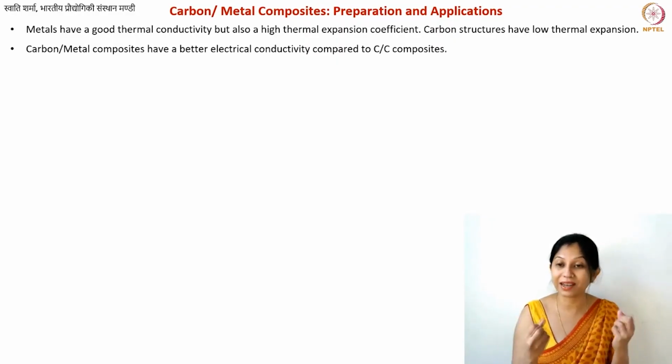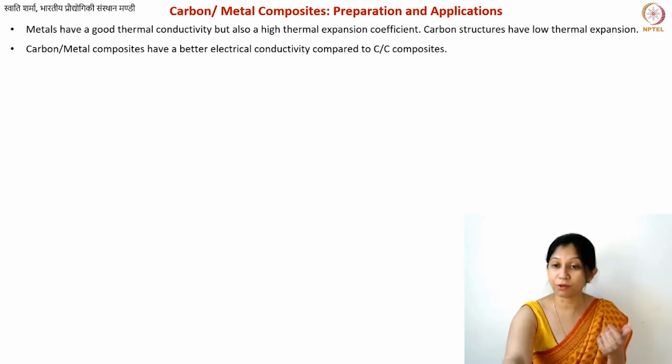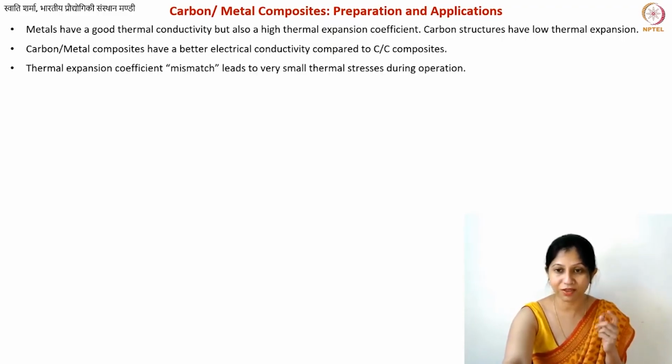can do is add these carbon fiber like materials, because we know this very well that our carbon materials have a low thermal expansion coefficient and they are very good at withstanding thermal shock. And that is why now you can have good electrical conductivity, so basically the property of the metal, good thermal conductivity, but a low thermal expansion coefficient. Okay, so this is why we need these kind of materials.